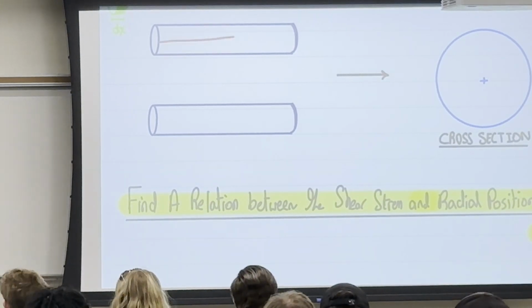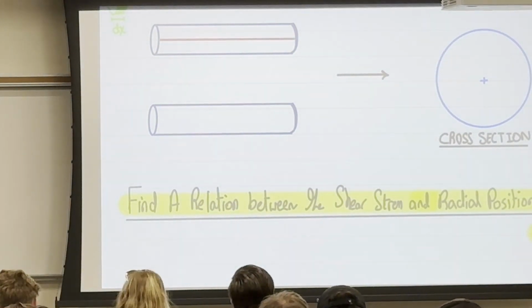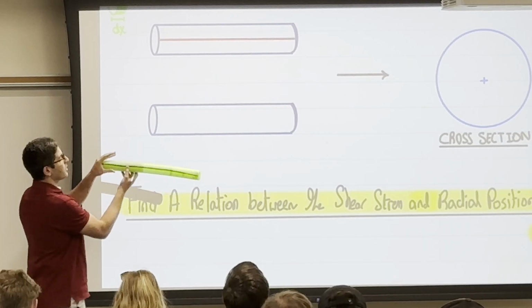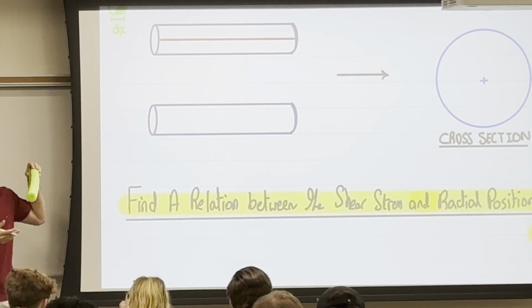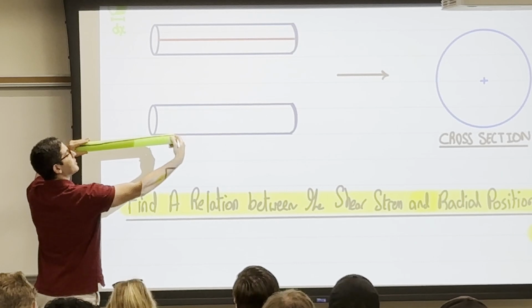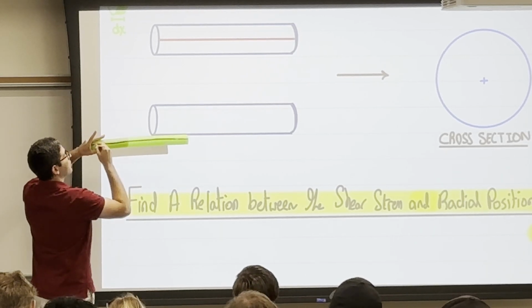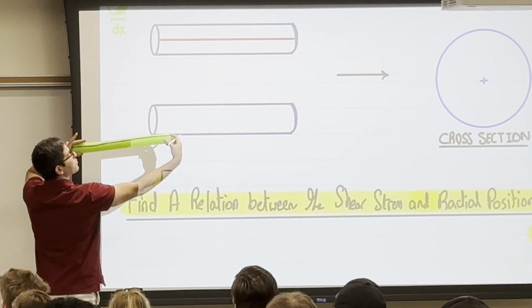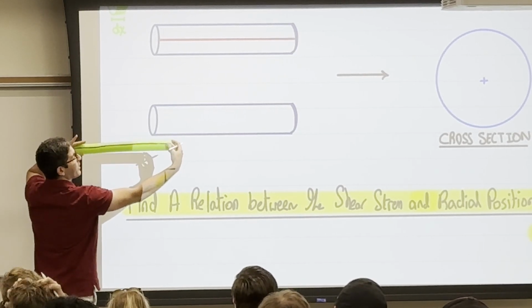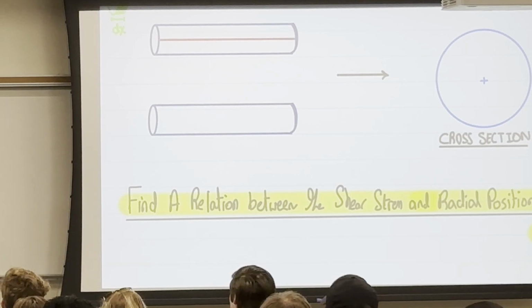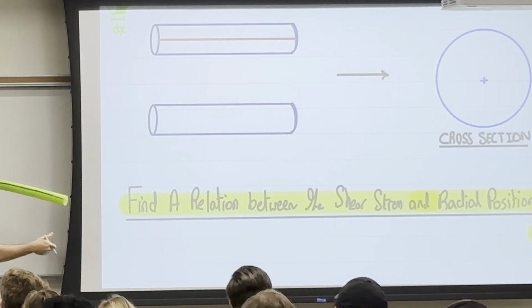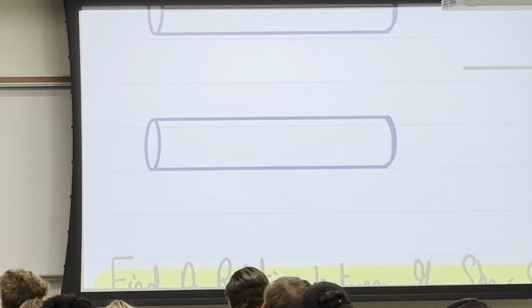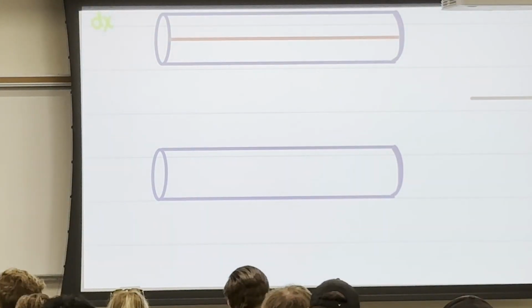So imagine I have a line like this, which I drew here, and I fix one location, and I will bend the other, and bend it about z. And when I say bend it about z, it's a torque, or a torsion, right? So what's happening to this line? Yeah, this line starts from the original axis and starts to bend like this, right? And the reason why it returns back to its own position, you all know, is because of the modulus, right? Because we are still within the linear elastic range, right? So you all agree with me now. When I apply a torque, this red line will be like this.